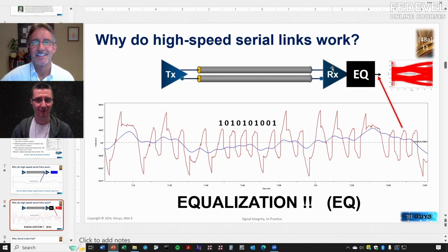This is very interesting because right now, for these lower frequencies, everyone is simulating on the input of the chip or IC, and suddenly this kind of measurement or simulation on the input of the IC is kind of useless. Well, think of the big BGAs, right? You can't go measure there anyway. You can't get a probe into these things.